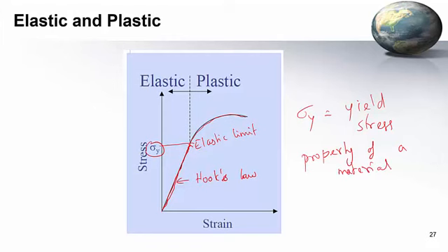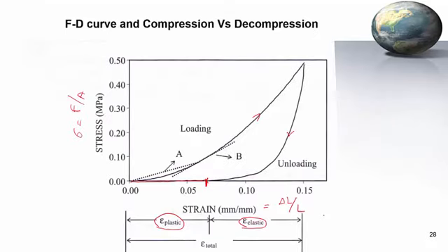So if you are designing a material that is going to undergo load in a mechanical system, let's say to harvest, you want the stress to be below the yield stress because you don't want a permanent deformation. If it is a bridge, when the truck goes by, there is going to be a little compression on the pillar, but you do want it to rebound within the elastic limit so that when the next truck comes in, it presses it and it rebounds back, and there is no permanent damage, and then it can last for a long time.